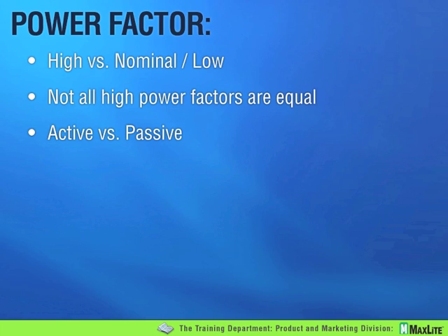So when a discharge lamp like a fluorescent is switched on, it draws apparent power from the mains, from the circuits. The apparent power actually has two components. One is active power, which is the actual power being consumed for the lamp that is illuminating, and the other is reactive power, which is feeding the electromagnetic circuit or the control gear and the like.